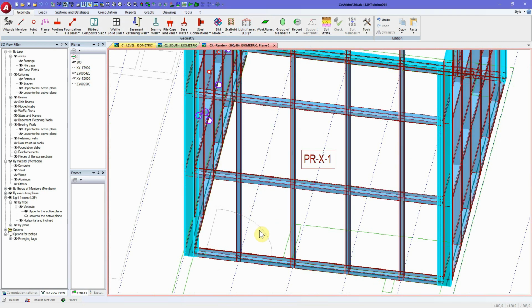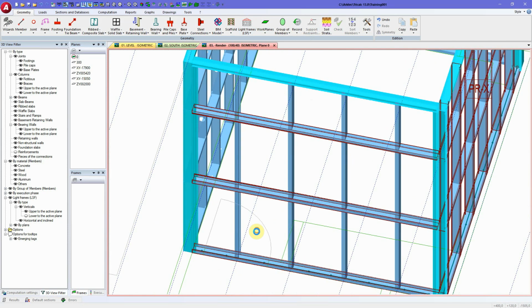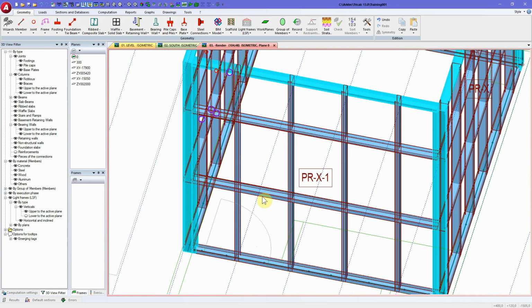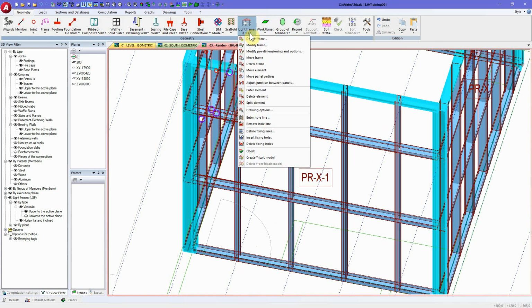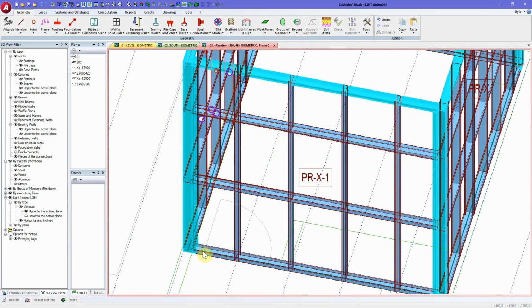and just going to change here the drawing options, not to use the green line, the green color for these profiles. So I'm going to create this door here the two ways. First way, with the wizard. I can see the objective, our purpose is to create here a new profile here at the left and a new profile here at the right of the door, and terminate the wall, let's say, in this horizontal beam here.